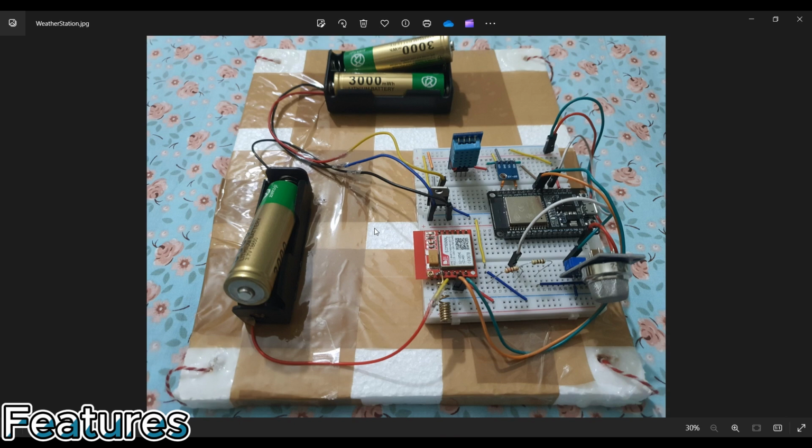But for now I don't have any kind of pocket router, so I couldn't proceed with the IoT based approach. So there is another approach that you can follow, which is by using the NRF transceiver, making a ground station. So what the NRF transceiver does is that the transmitter has to be attached on top of the board, and the transmitter of the NRF module will be transmitting the weather parameters to the receiver, where the receiver is another NRF module that will be situated on the ground, simply known as the ground station.